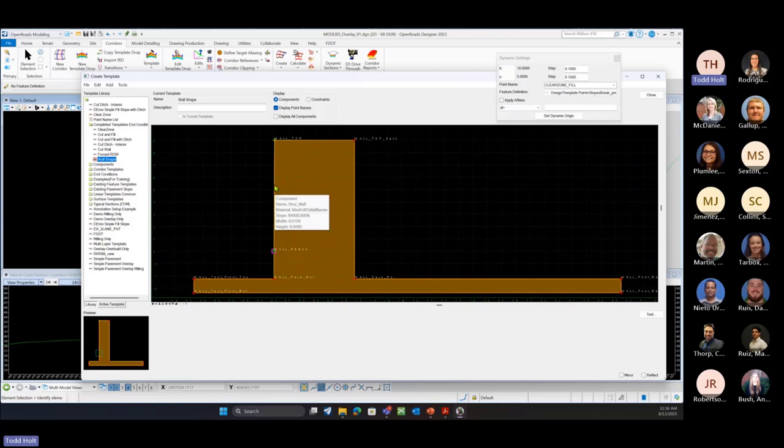I changed it over to your feature definitions. But what we're going to do is build an end condition, and it's going to be a 50% slope from our hinge point or our slope. So from the start, we're going to go 50% up. And if it finds the feature definition right away within that 50%, we want it to draw this wall.